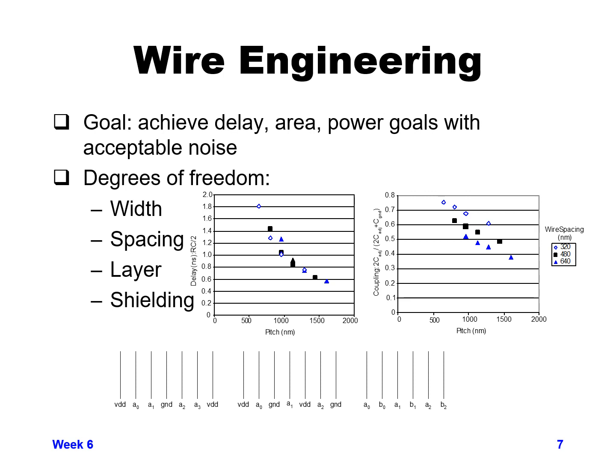So this is called half shielded, where one side is a shield and the other side is a potentially switching wire. This gives you a reasonable number of routing tracks, but also a reasonable number of reasonably well shielded for noise.